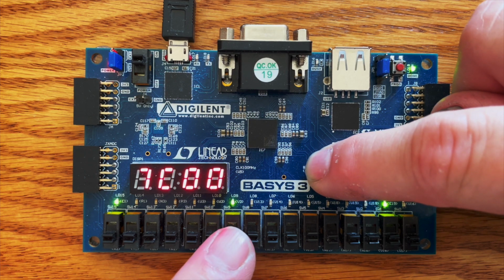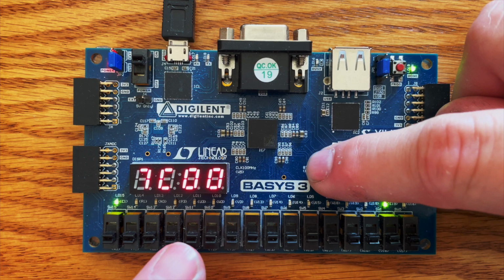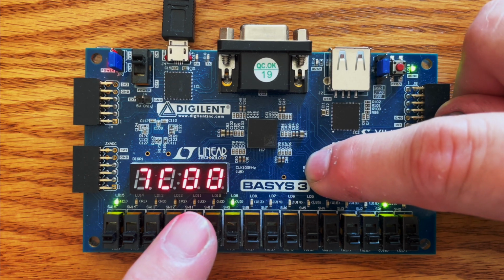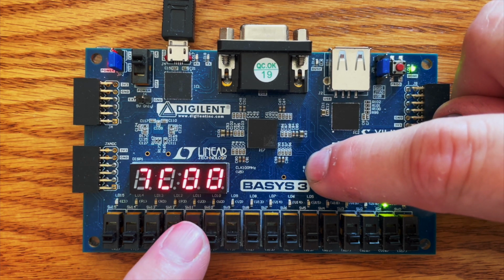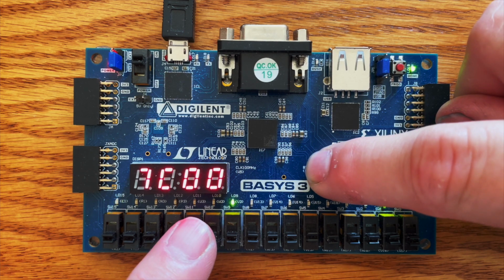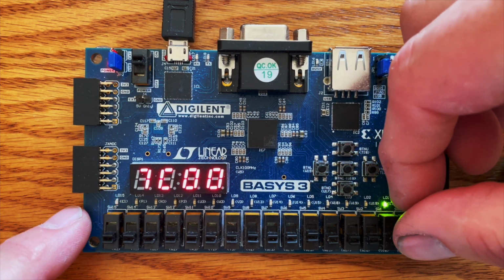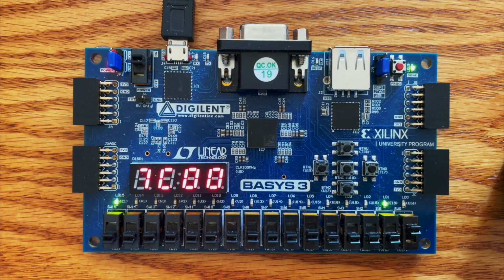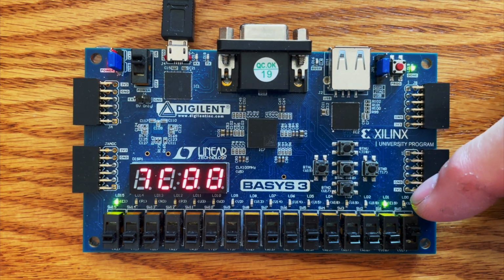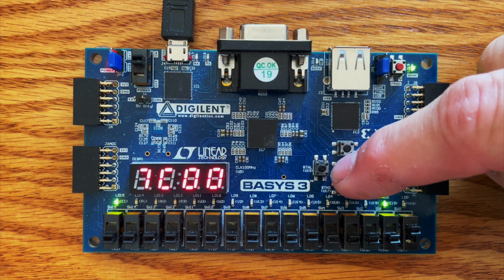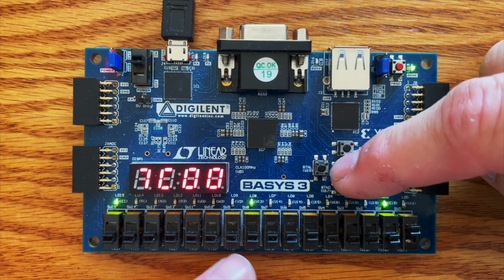While the left push button is pressed, you'll see LED 9 lit. Like pushing the right push button, you'll see LED 11 flash on, then off. To change the rounding mode, set dip switches 0 through 4 with the desired value. Remember, one and only one of these switches should be on when selecting the rounding mode, and then press and release the center push button.